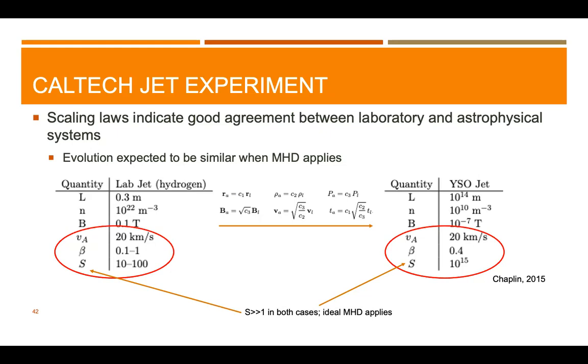It's going to be capacitive, et cetera. So going in, it's very difficult to compensate for the impedance that you're adding to the system that doesn't exist in the astrophysical system. You can back it out. You can actually correct for it. The dusty plasma experiment that we have required an impedance matcher specifically for that reason. Otherwise, you'd end up coupling in all of these strange effects that you just couldn't live with.